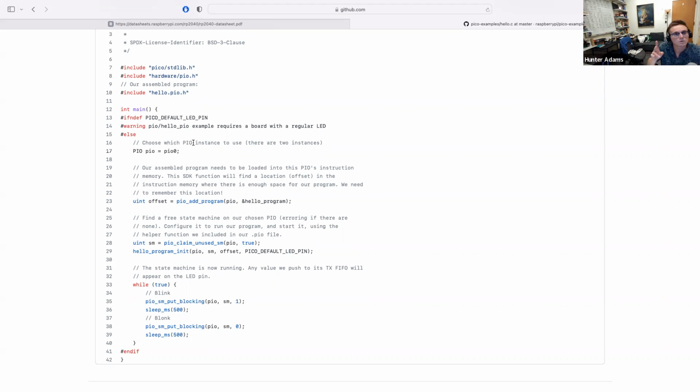Remember that there are 2, so we're going to use PIO0 or PIO1. In this case, we're using PIO0. We then add that program, the hello program that we just wrote, to PIO0.